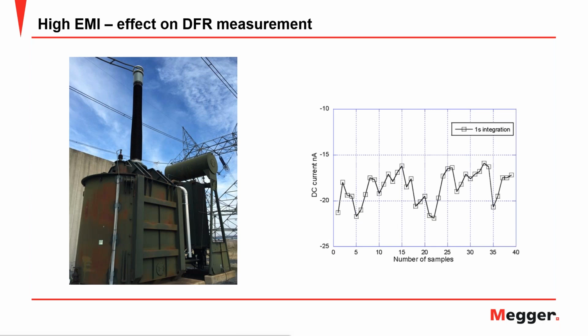And of course, one of the problems that you can face with trying to do a low voltage test is if you go to a high electromagnetic induction area, right? And you try to run a low voltage DFR test. Noise is something that we cannot avoid. The only thing that we can do is minimize the effect of noise in the substation. One of the problems that we have here is that if you compare your power transformer, you're talking about nanofarads insulation.